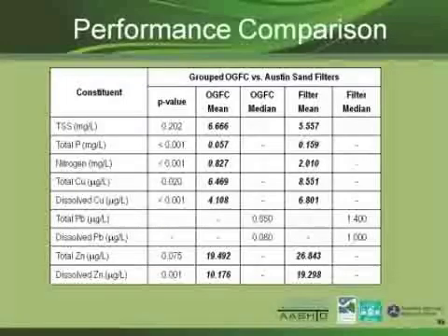And so we took the California data, and also in California we'd done some monitoring of sand filters for Caltrans years ago. We had 5 sites. In this table I'm going to compare the discharge concentrations for sand filters from that Caltrans study, which are in this column and these 2 values, to the discharge concentration from the permeable overlays, which in Caltrans speak is OGFC instead of PFC. And this is a list of constituents for which a sand filter will achieve statistically significant reductions in concentration.